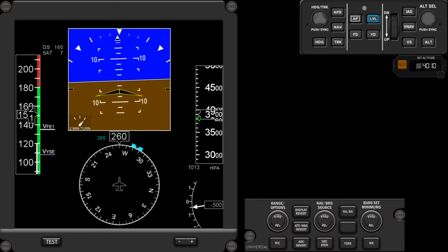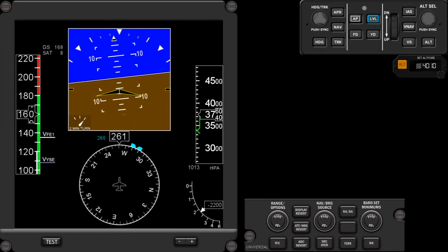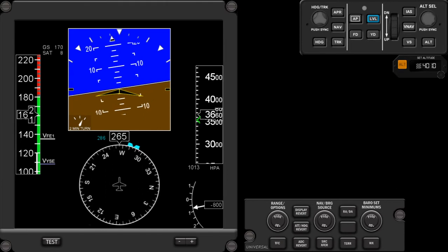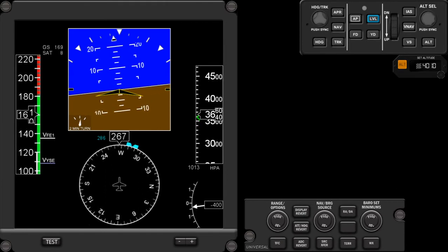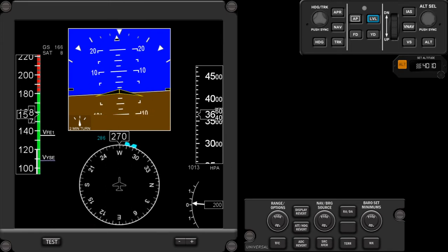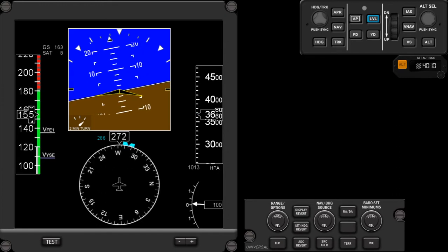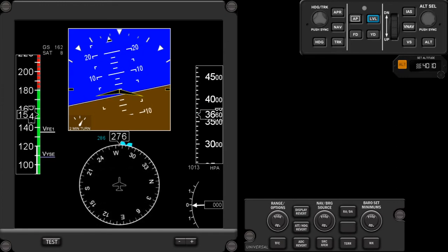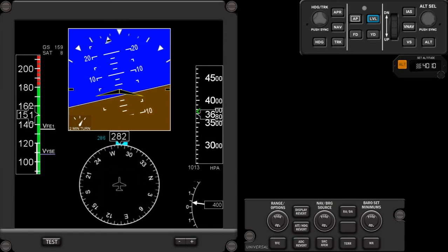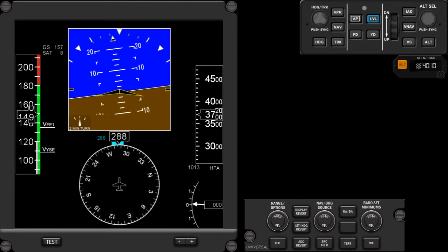So as you can see on the left side there is an airspeed indicator. If I speed up, the airspeed is rising. You can see some airspeed bugs, which is the VFE1. That's the flaps extension first position, maximum airspeed. And there's also the white bar from 120 knots down, which is the full flaps limiting speed. The other bug is the VYSE, which is the best rate of climb on single engine, as I'm flying a twin turboprop right now.